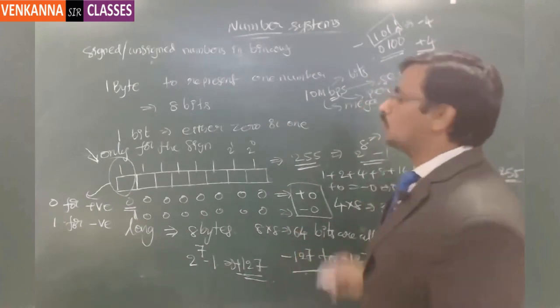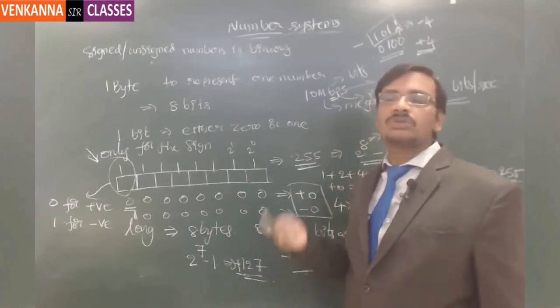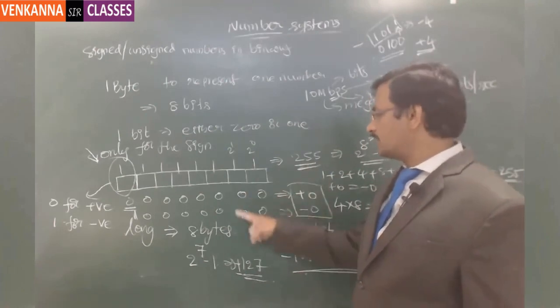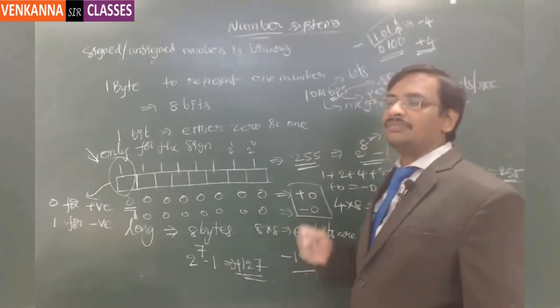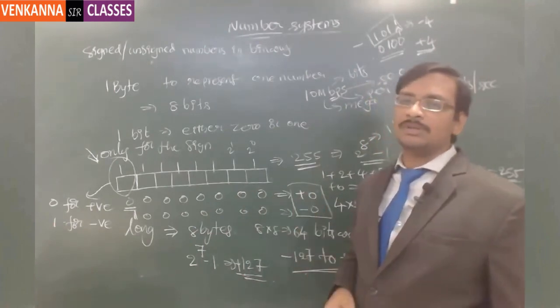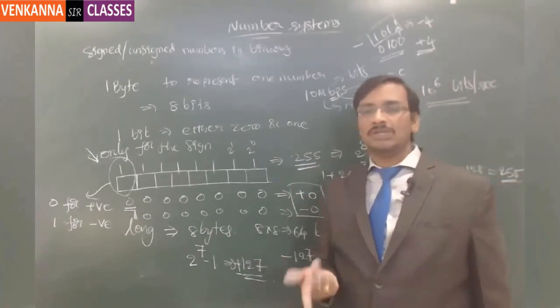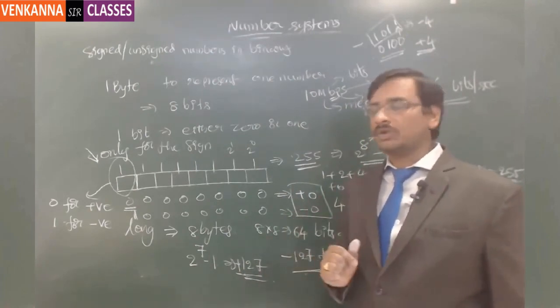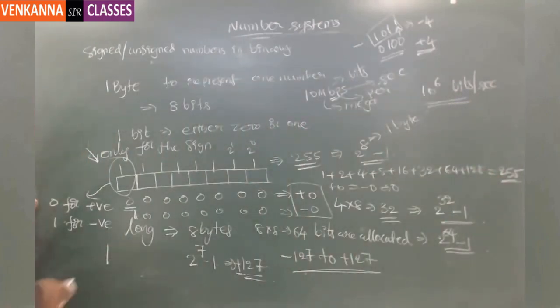So there are two methods people came up with. Those are 1's complement and 2's complement, which you can make use of to represent the negative number. Got it? With the help of 2's complement, we tried avoiding two different places for the 0, and gaining easiness for the circuit design purpose, which is the adder circuits. With those advantages, 2's complement became the most popular signed number representation. Got it? Suppose I take 4 bits. First you note this down, I am going to erase it and then explain it.